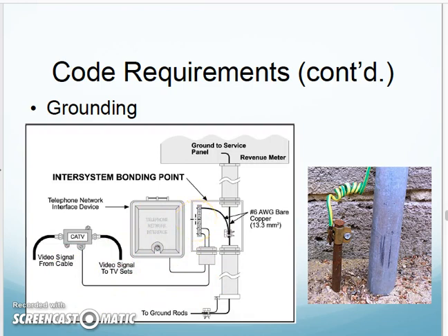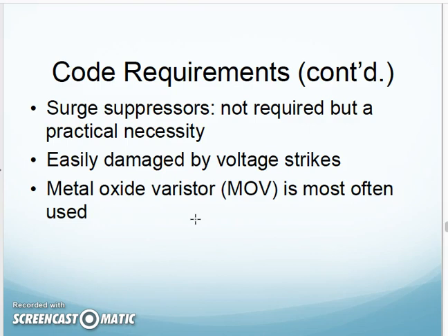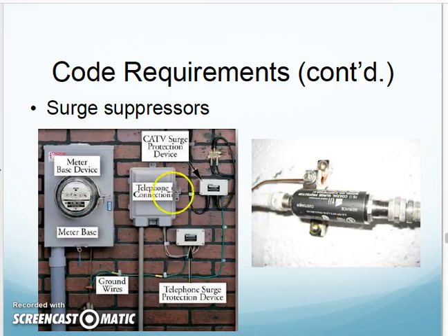It's mainly worried that the line hanging between poles is susceptible to lightning strikes and surges. We need to make sure that is protected from that. And with that mentioned, with surge protection, we need to make sure we do have surge suppression in there. And actually here on our picture from before, it shows you cable TV surge protection, and here is an example of one. Little surge protector, coax coming in, surge protector, coax going out, ground wire coming off of here that will be going to the ground wire at the side of your house, picking up that surge and sending it to ground.